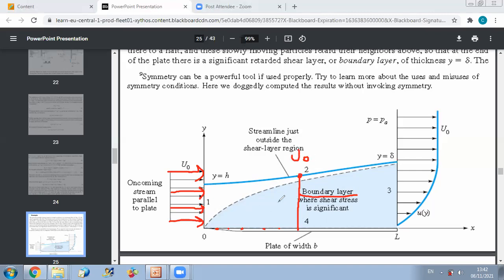But the mass flow rate is constant, because from continuity, if I take any control volume between any two sections in a steady application, and here I have an incompressible flow, I should have m dot in equal to m dot out. So at any section, the mass flow rate is the same.